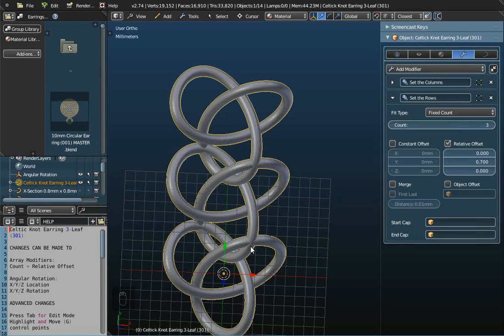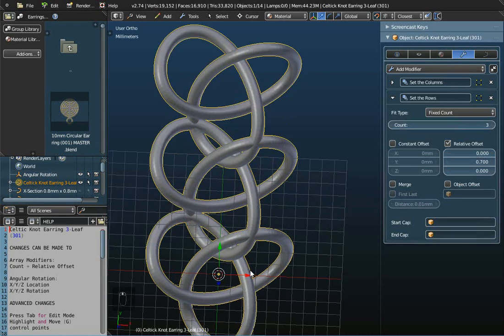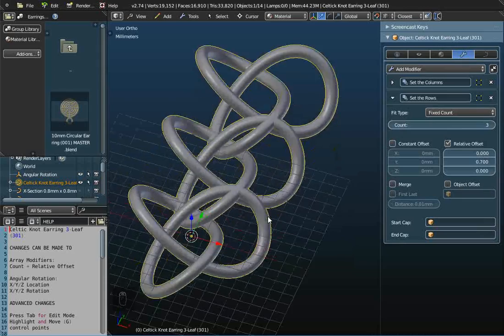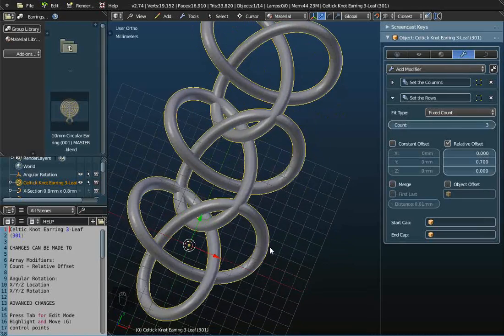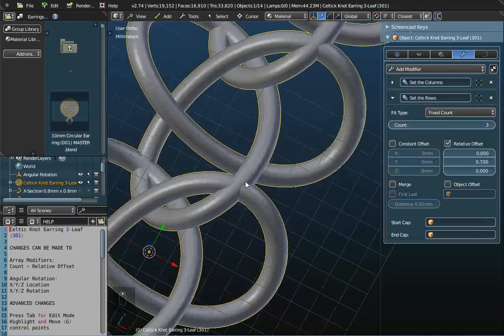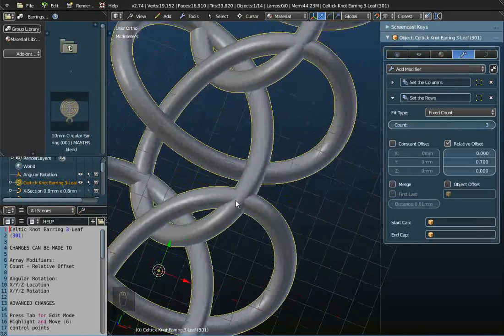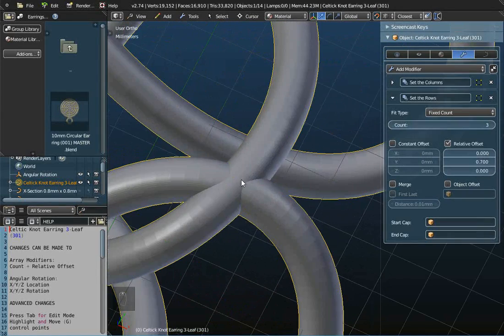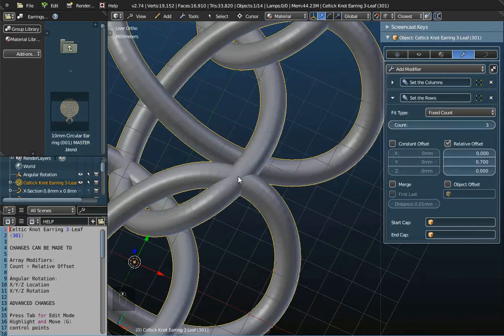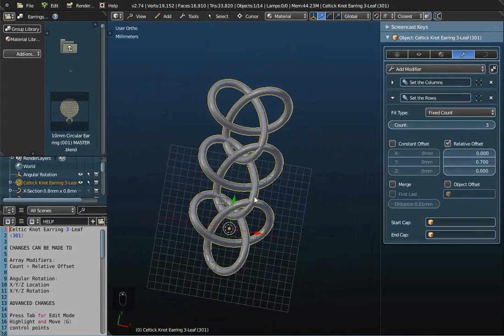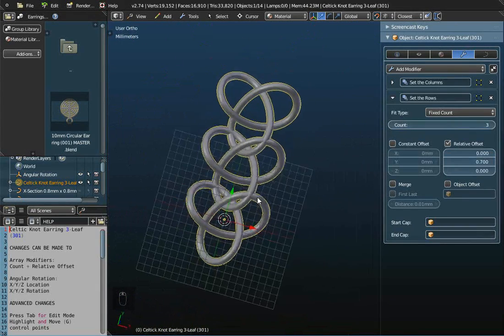if they're not overlapping sufficiently, the object when it's printed could print in more than one part, or it could print in such a way that it easily breaks. So you do want to be careful and look for a good overlap, which we've got here at that setting.